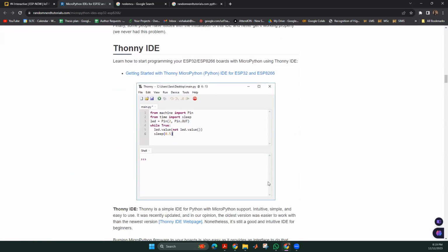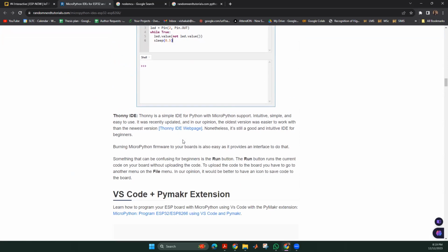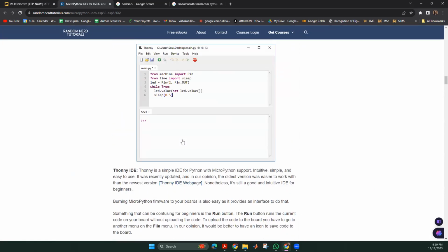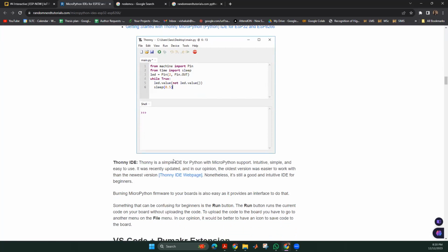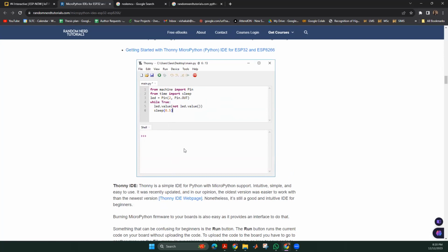And after you install that, you need to run a certain sample code and see whether you can get the correct output that you expect or not. And then you can also check whether there are any problems with the port that you are connecting your microcontroller to, right? So you can check whether you have any problems, errors coming in the serial monitor.